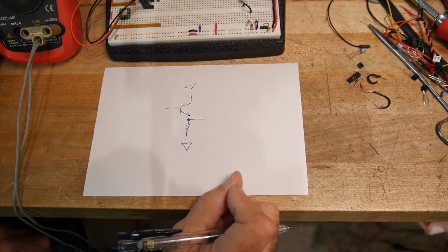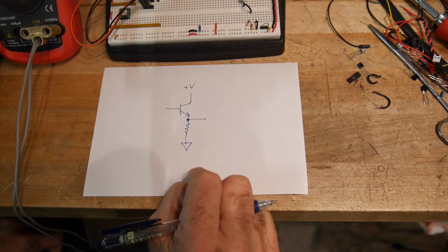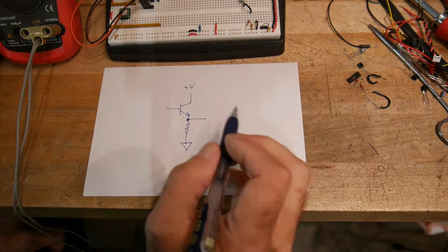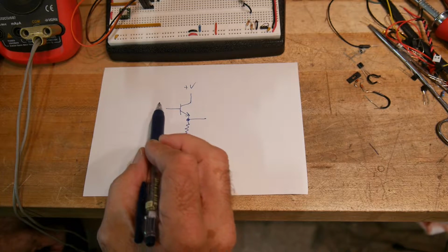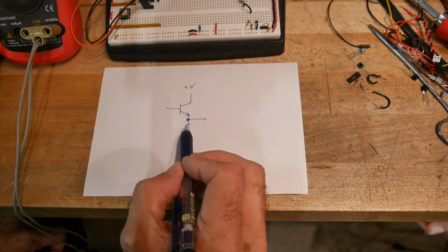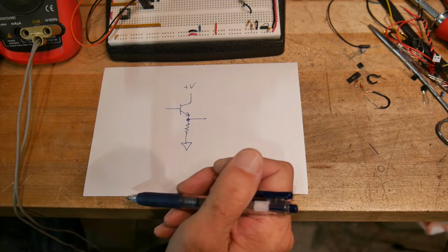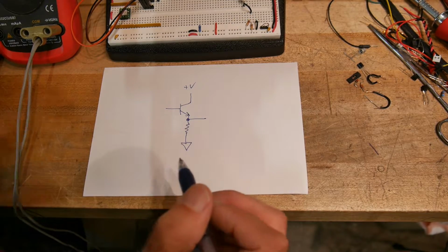It'll be 5 volts when we're breadboarding it up, but 5 volts in, and we have a transistor, and this is an emitter follower. So we've seen this before. Whatever you put here kind of ends up here, so it's a gain of 1 amplifier. But if we take a look at this in DC conditions,